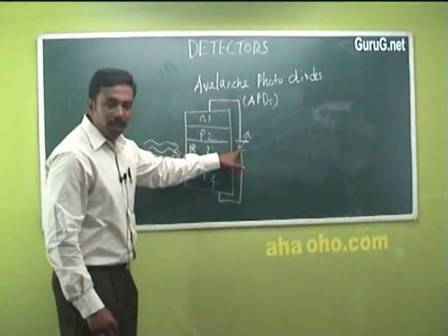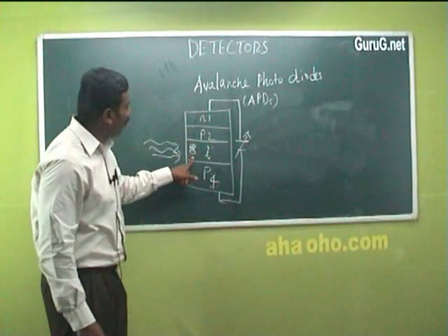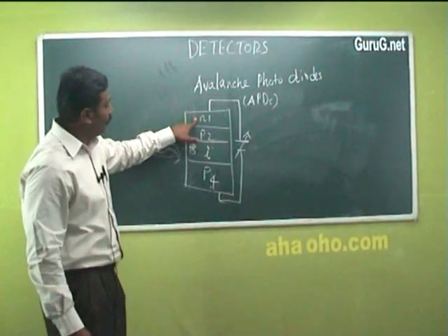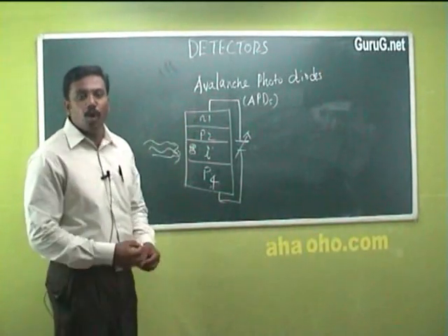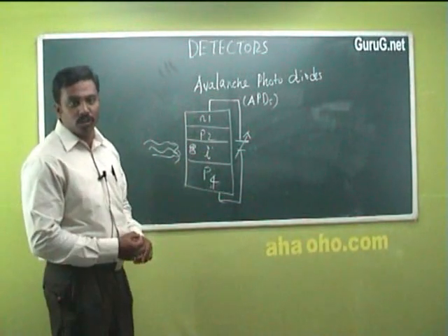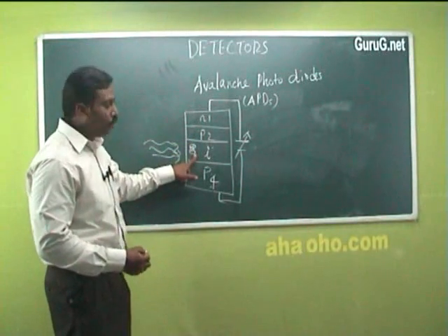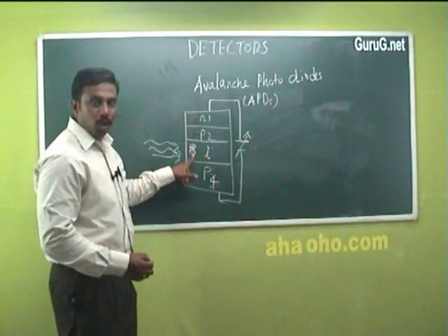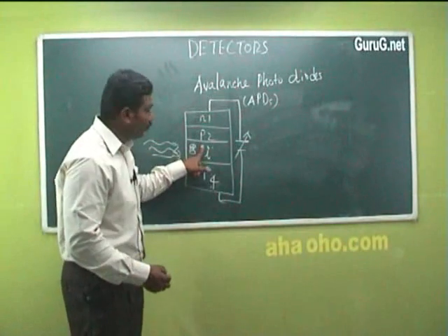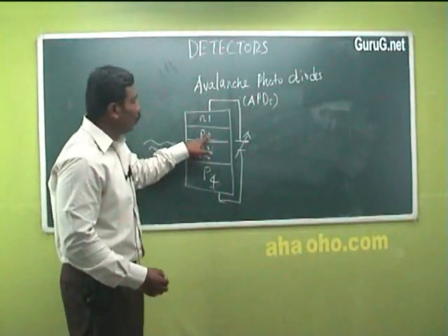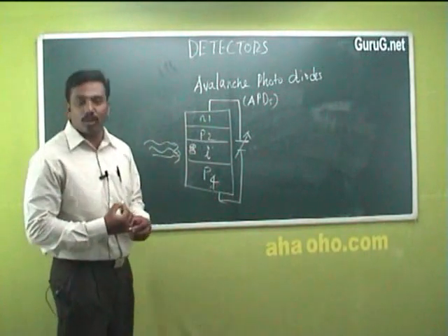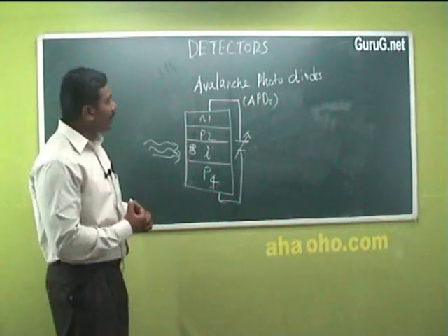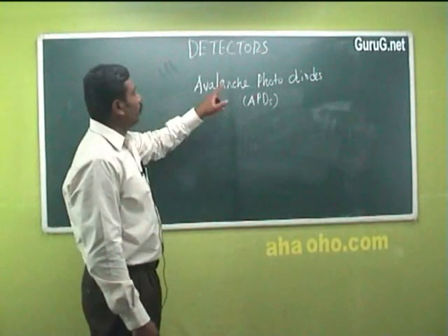When the reverse bias voltage is increased, the electron hole pair created is drifted from the intrinsic region through P2 and N1, and they collide with the free electrons or valency electrons, creating more conduction electrons. These conduction electrons are the basis of the avalanche photodiode.